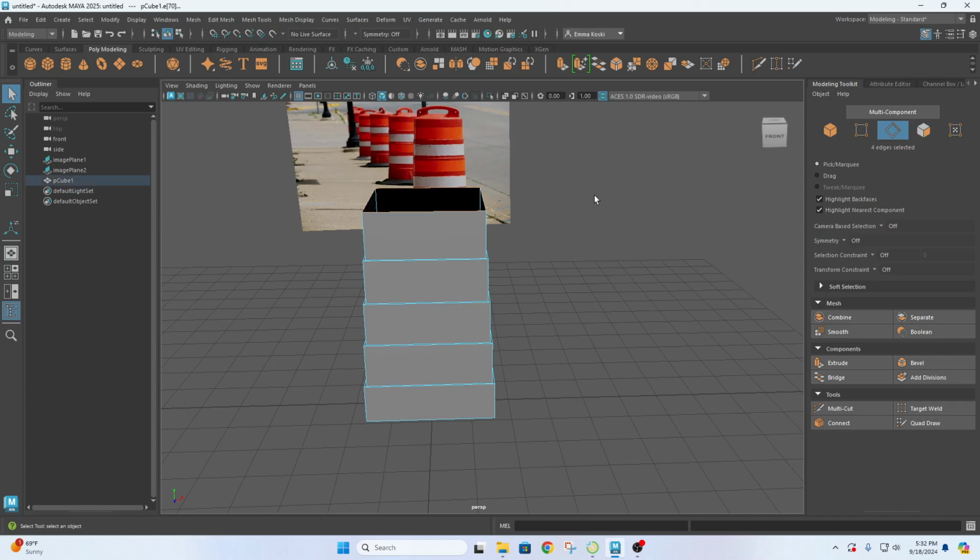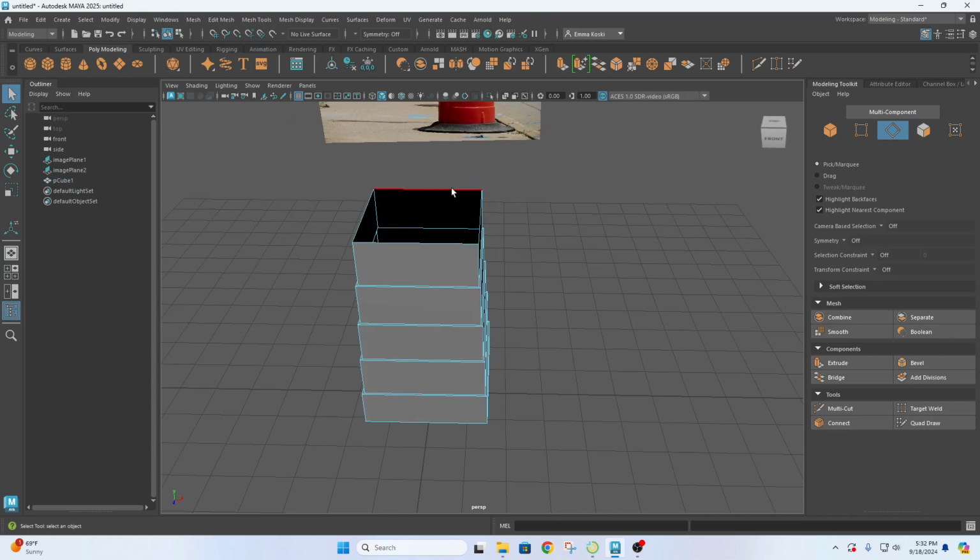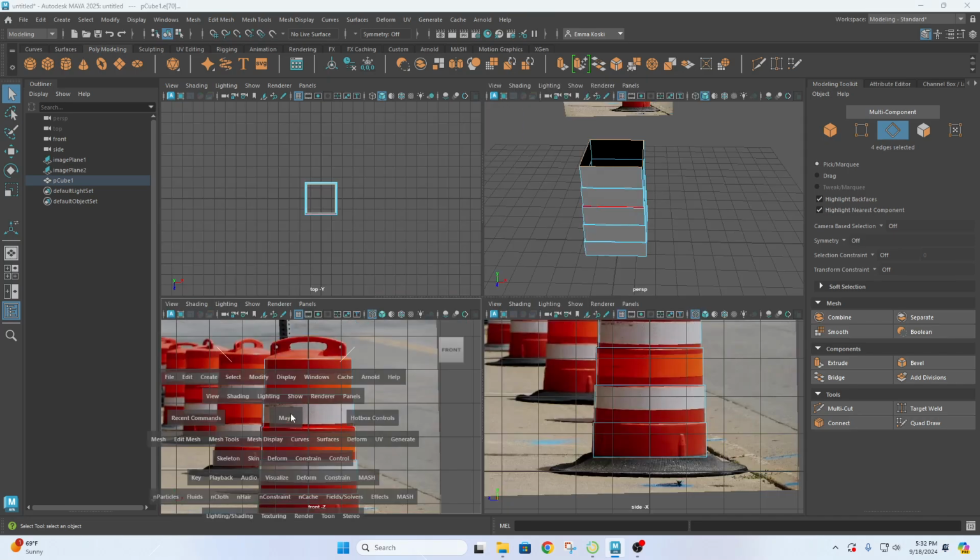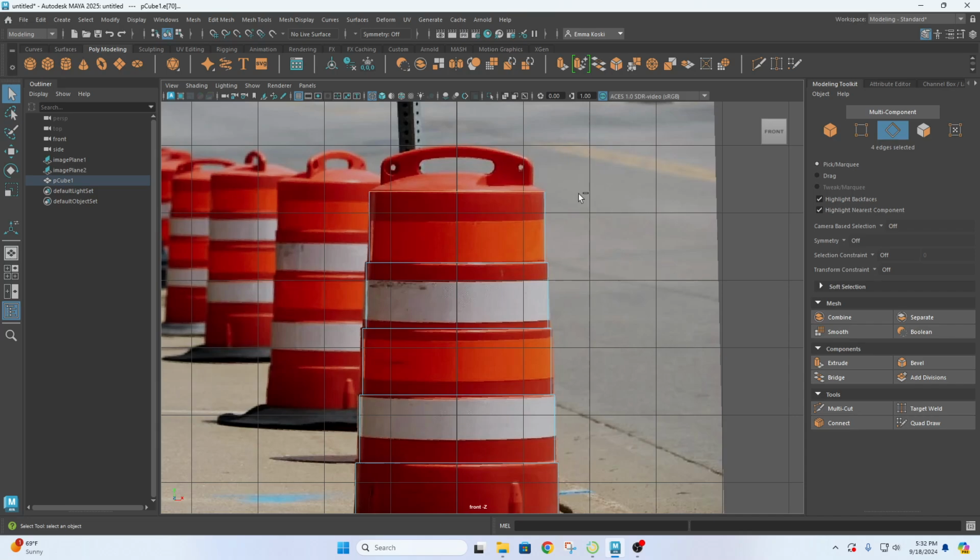So we're going to do edge selection again. Let's double click one of those edges to grab that top edge loop again. And we're going to extrude again. Control E, so you can extrude in either view. Again, you don't want to use the widget that comes with Control E though, with the extrude tool. We're going to use W. And this time, let's go ahead and pull this up to right about like halfway up that curved portion.